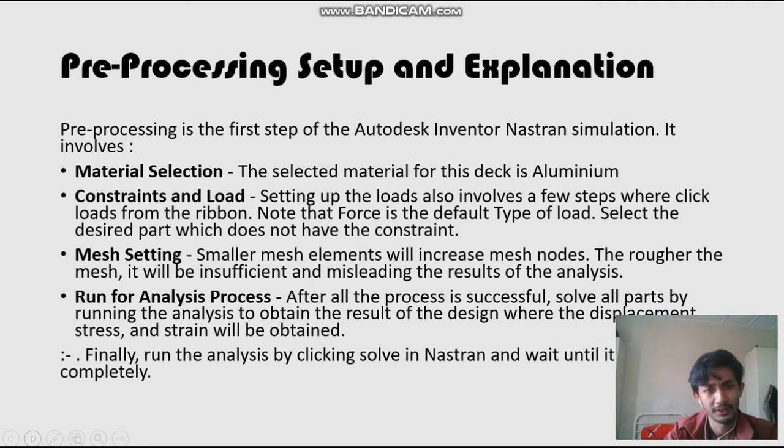Okay, the pre-processing setup and explanation. The pre-processing is the first step of Autodesk Inventor Nastran: material selection, constraint and load, mesh setting, and run for analysis. The first one is to select the material, and for this deck it is aluminium.